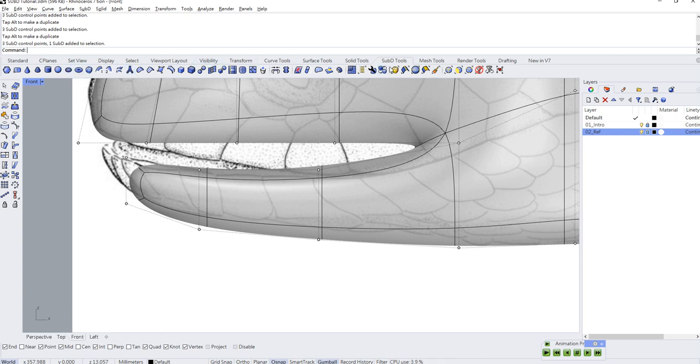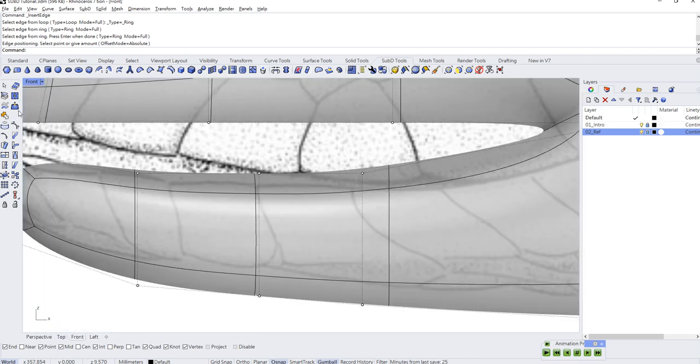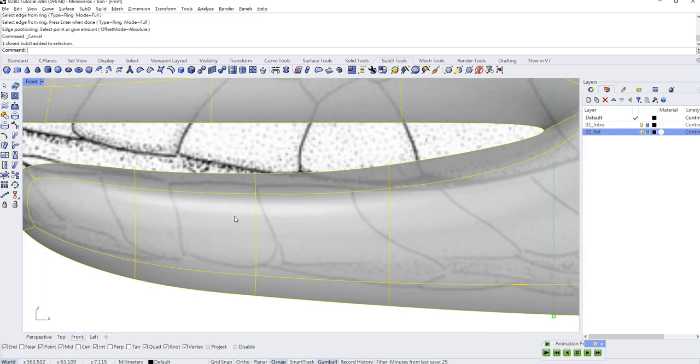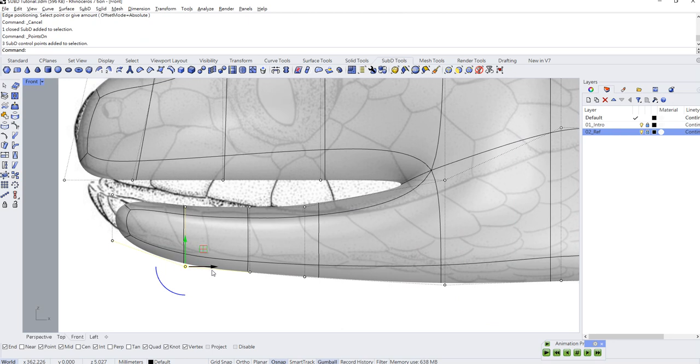So let's go to subdivision tools and, using your right mouse button, choose insert edge loop. So insert the edge ring, choosing this one. And I want to create an edge right here. So let's choose these sections and press enter. And you can close sections. So now you have more face to control. Press F10 again to do some manipulations.